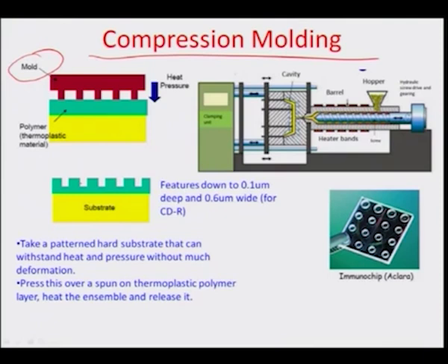Another very interesting process is injection molding, and this is illustrated in this figure here, where you can see the feed of the polymeric material happen through this lead screw, which pushes the polymer melt. So, in this region there are heater bands which would melt the polymer, and the polymer melt is pushed forward into this die cavity, and the die cavity has some release agents on both sides.